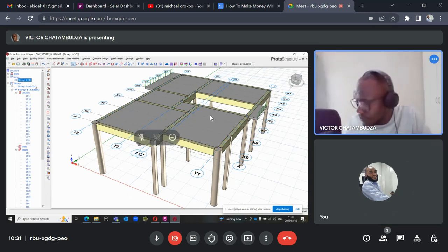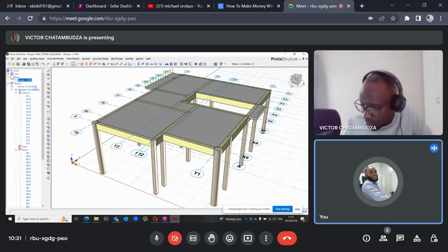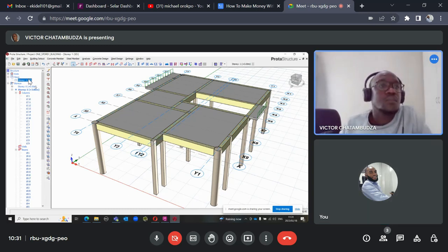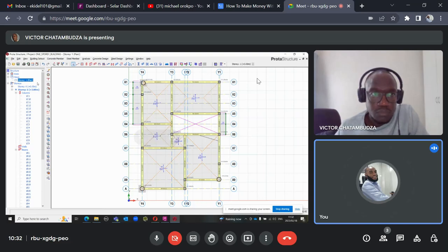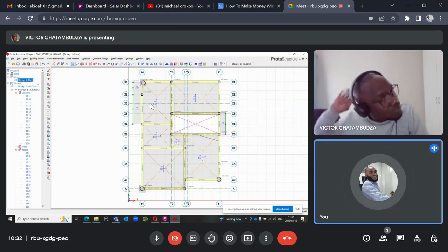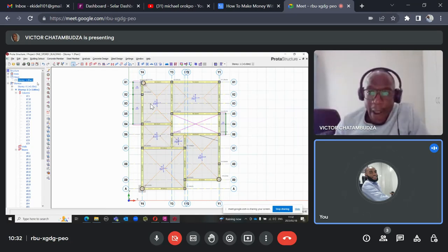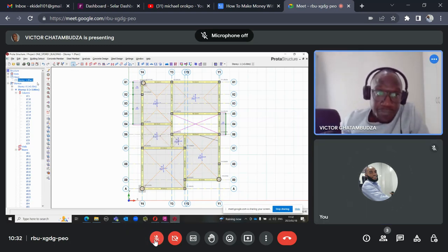So now go back to your plan view, still in that place, right click there and say plan view or plan. Now we want to insert our story. Once you're done with your first floor plan, now begin to insert our story. To insert your story right now,